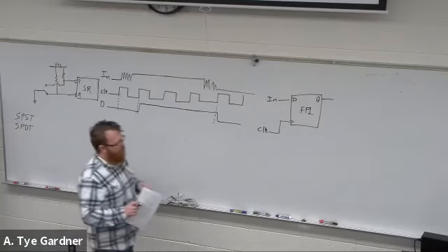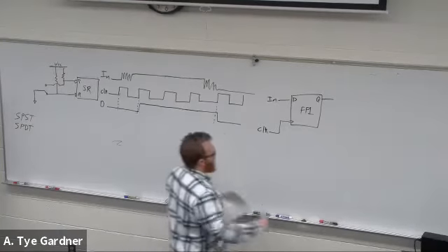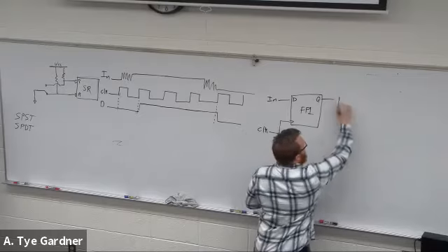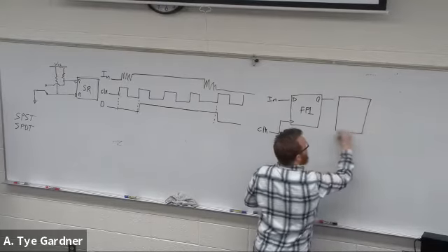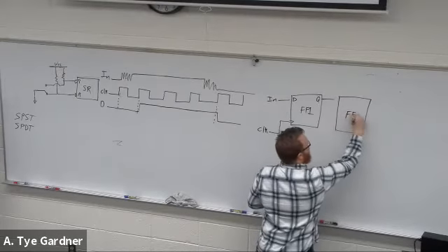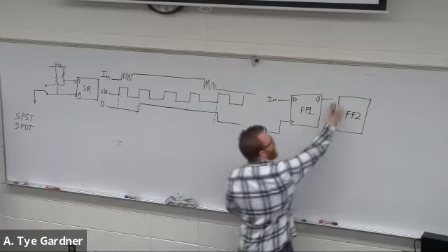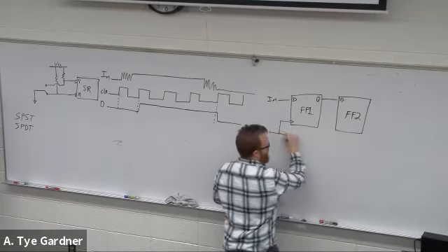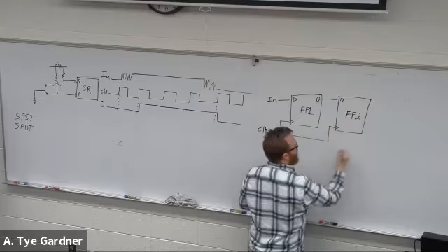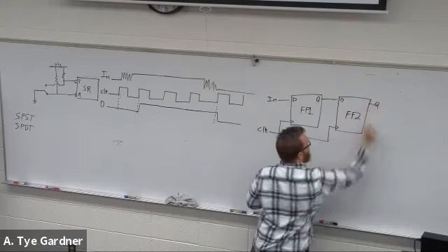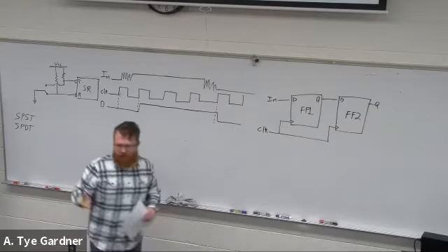Okay, well, we're going to have to be stuck with that for a while, but let's go ahead and address the other issue, which turns out to be really easy. So we just throw in a second flip-flop. D, let's just take the same clock. Q. Okay, so now what does this change?